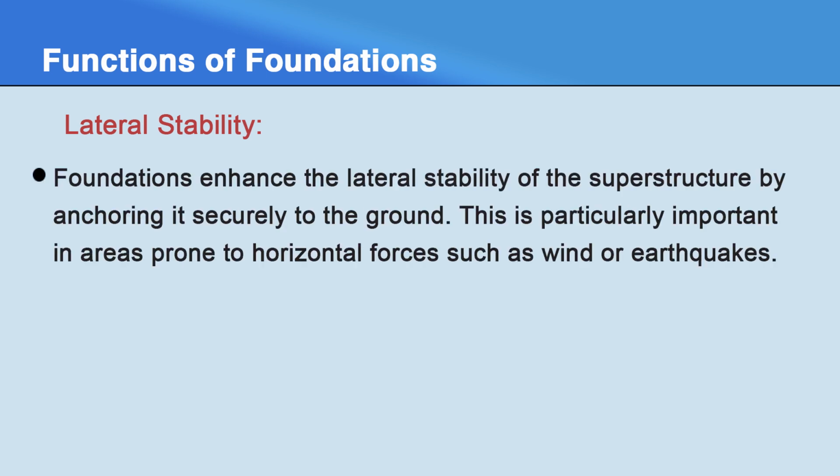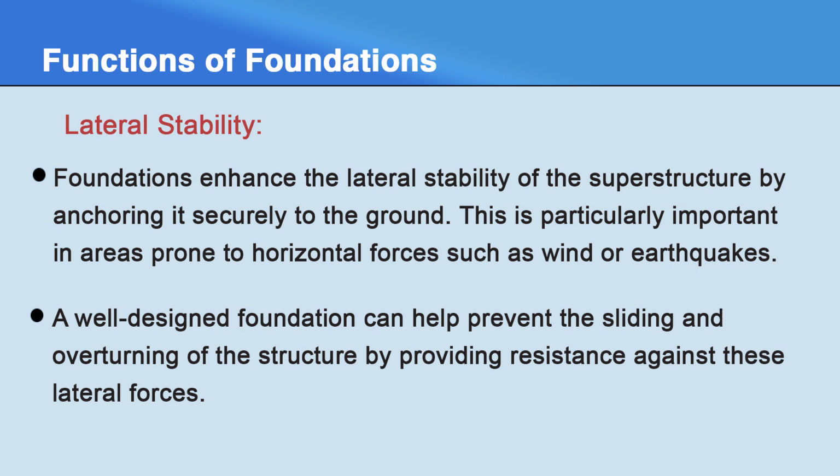Foundations enhance the lateral stability of the superstructure by anchoring it securely to the ground. This is particularly important in areas prone to horizontal forces such as wind or earthquakes. A well-designed foundation can help prevent the sliding and overturning of the structure by providing resistance against these lateral forces. This is achieved through various means such as increasing the depth and width of the foundation or using deep foundation systems like piles and anchors.